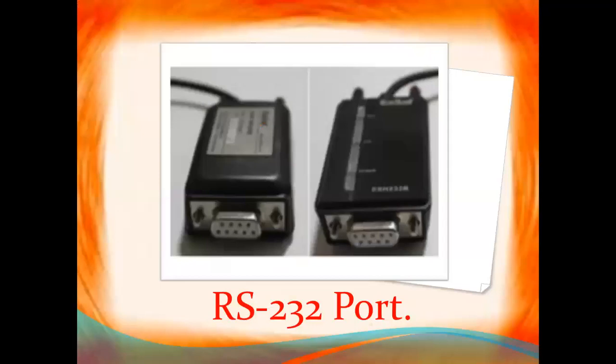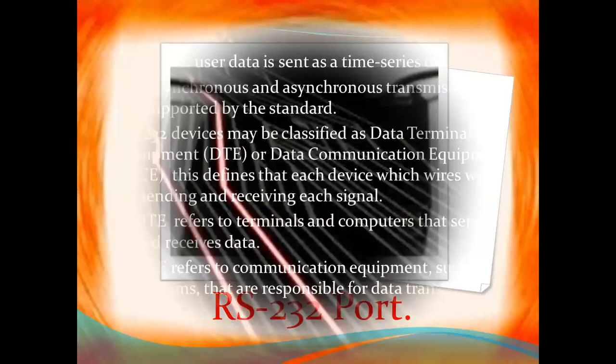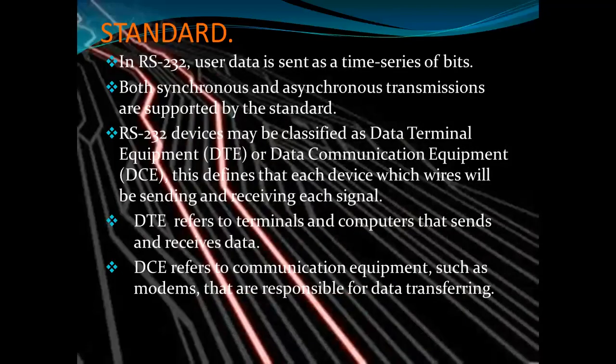So these are the RS-232 ports. D-type ports are there, with 9-pin and 25-pin connectors. In RS-232, user data is sent as a time series of bits. Both synchronous and asynchronous transmissions are supported by the standard.